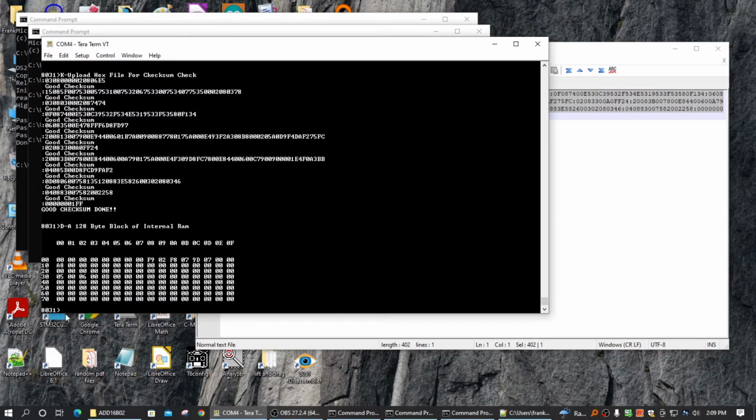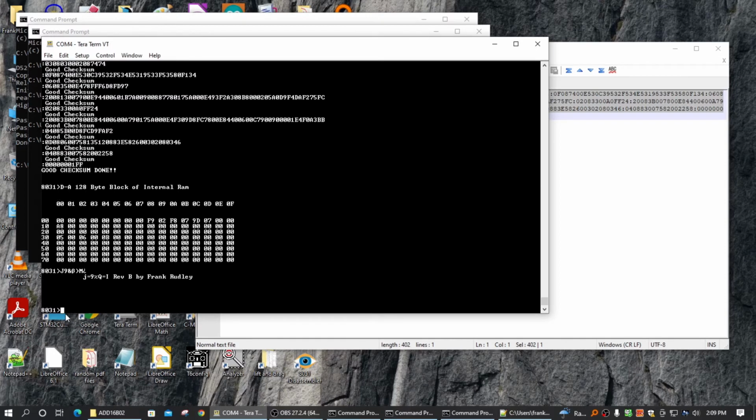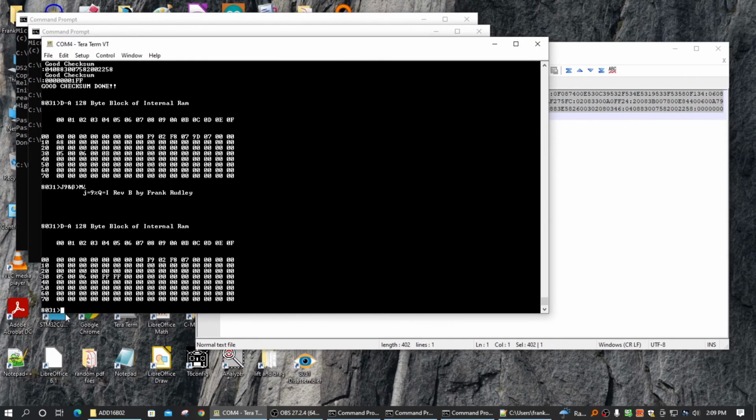But now I'm going to run the program. So I hit J to run the program. Then I interrupt it by hitting a reset. Now I'm going to hit D again. So if I look at 30, I have the 5 and the 6. So this is 30, this is 32, and at 34 I get FFFF, which is -1 in signed math.